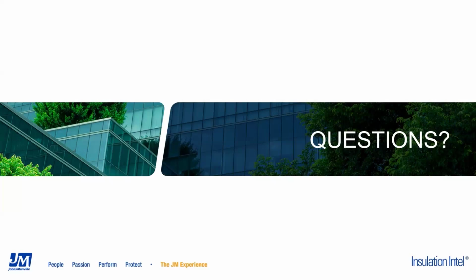Lastly, how do you quantify carbon emissions in buildings? That's another good question. And really, this is where we take how our buildings use energy, and then we have to look at what sort of energy they receive. So obviously, if a building is using energy by directly combusting things like natural gas, so think boilers, water heaters, furnaces, then we can directly calculate that.